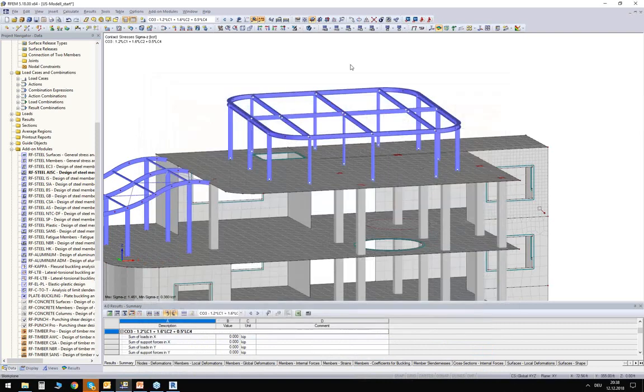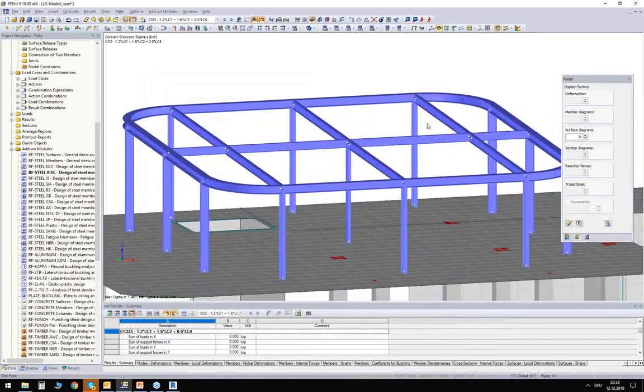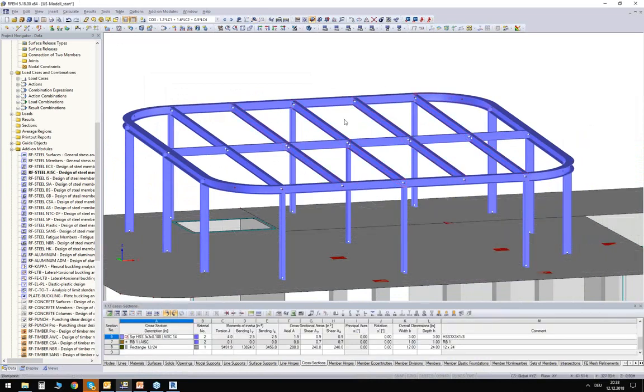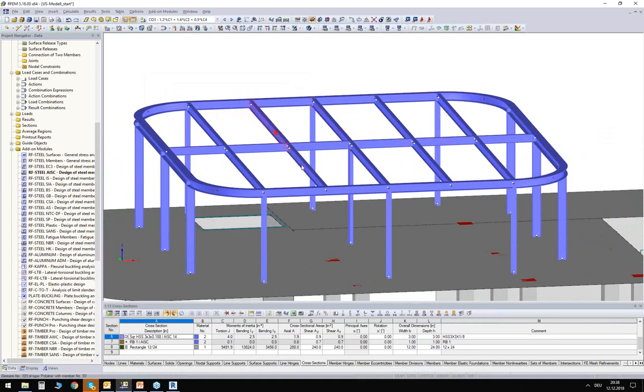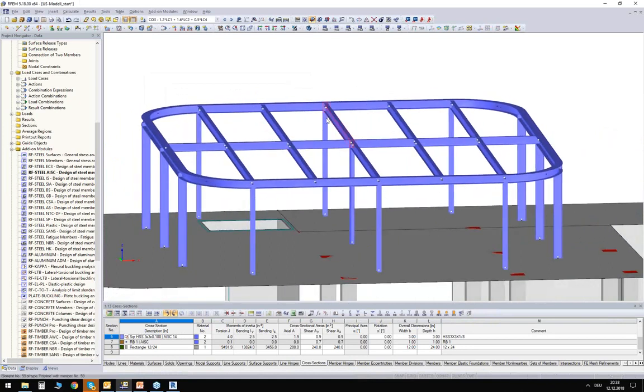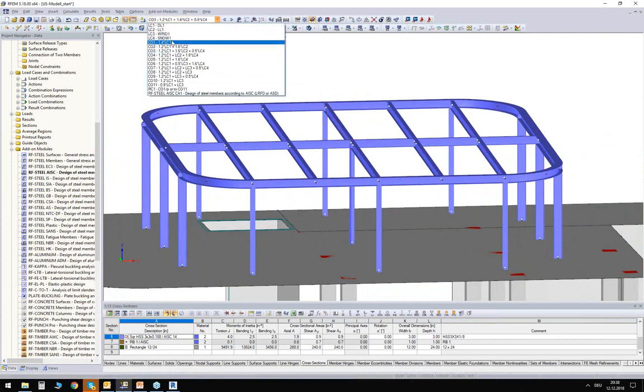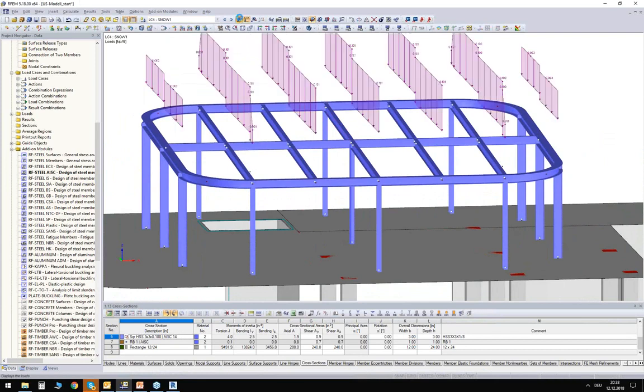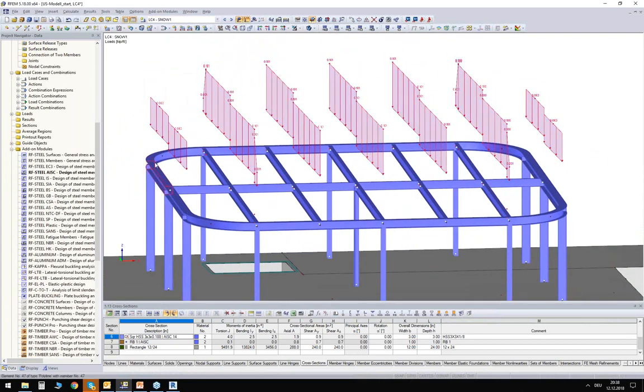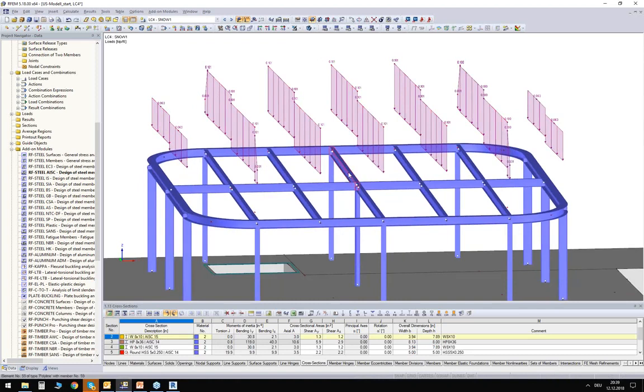So what I'm going to do here is apply additional beams in my roof. I just select the beams, and I use drag and drop to copy them. It's like a graphical tool to copy beams, and it's really quick and easy. By defining additional beams, I will spread the load. And this is something I want to show. If you remember, we defined here this generated load where we defined the area where it should act and so on. And this load is so intelligent that it recognizes these new members, and it will redistribute the area load to all beams now, to all slope beams.